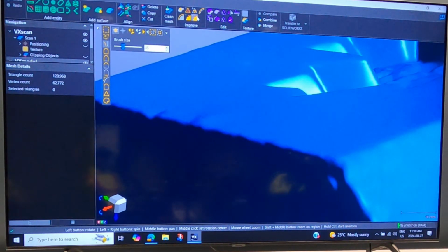And then we have the purple team, which we call edit. So that's where there's watertight, but it's also where you can mirror, scale, extend boundaries, and cut boundaries. You're veering off of the original part and you're making a copy. You know, you scanned a car. You want it watertight, but you want to print at 125, so you scale it down to 125 and 3D print it.